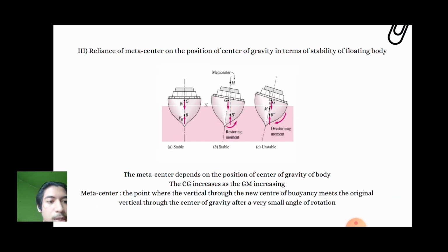From the diagram, you can see that when the body is in equilibrium position, the force of buoyancy Fv is equal to the weight of the body. W will be downward, passing through the buoyancy center B and gravity center of the body G. When the pontoon is tilted at a certain angle theta, the action line of W will not pass through B anymore, but rather through the new buoyancy center.